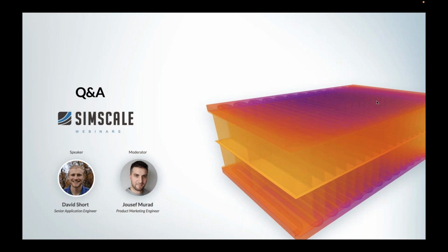And the way we can do that is either through volumetric heat sources, so giving some wattage to specific volumes. We can add surface-based heat fluxes, for example, for modeling the ambient natural convection effects like we've done in this model. So there's surface-based boundary conditions. There's also volumetric boundary conditions. Yeah, I think that's probably all I need to talk about in terms of boundary conditions.